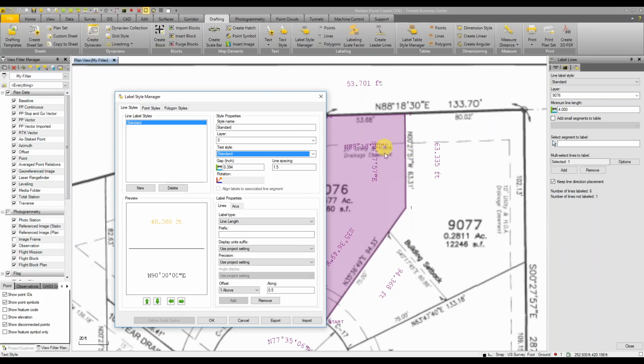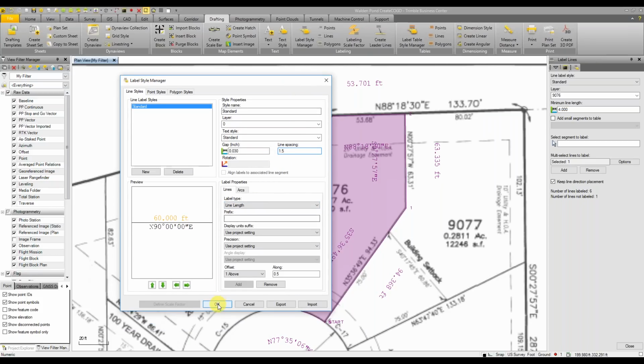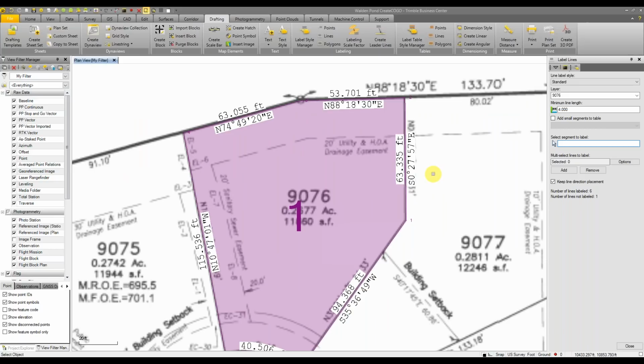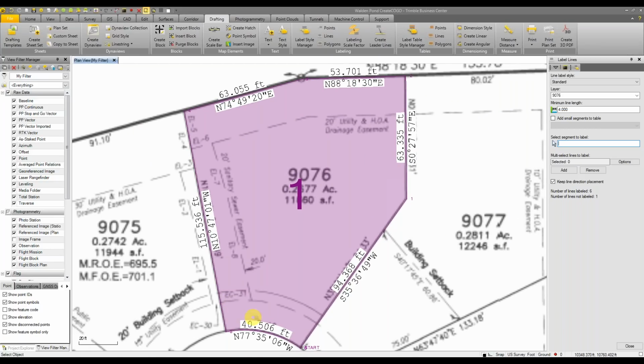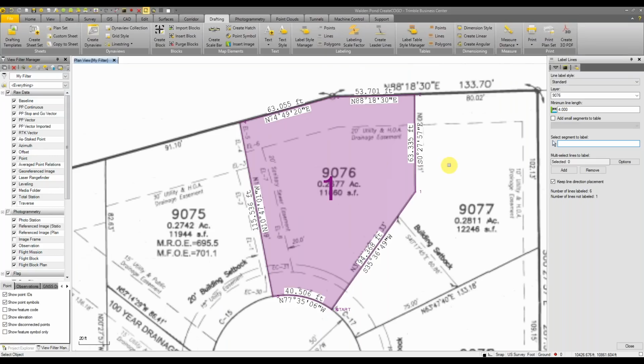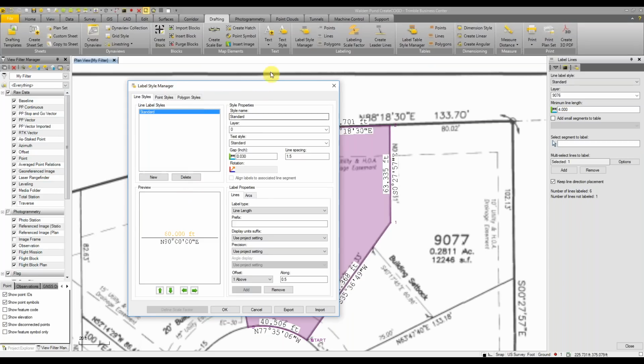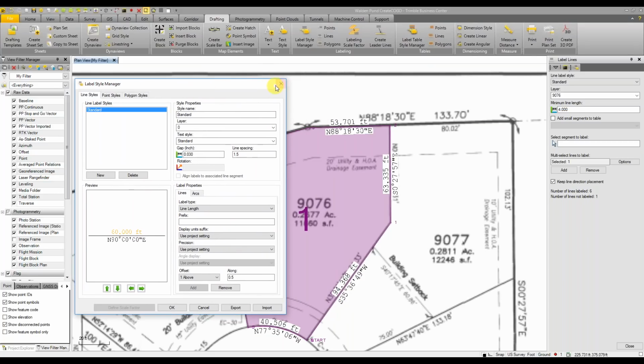There's our text size. That looks better, but our gap is still quite large. So let's change that. That's here, just below text style. And let's set that to something like 300. See how that looks. It gives us a preview of what the text is going to look like down here. So that looks great. Yeah, there we go. This is what the whiteout does. It blocks out any color so the text is easy to read. And it sets it so your text is always left to right or up the page. Consistency is good. So also in the label style manager, we'll come back to this.